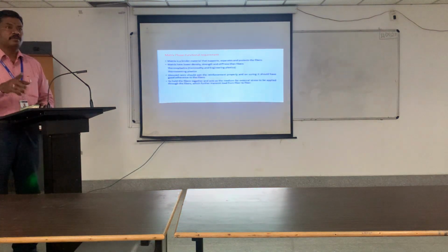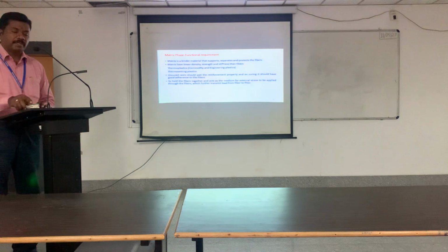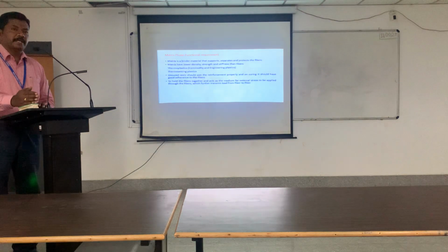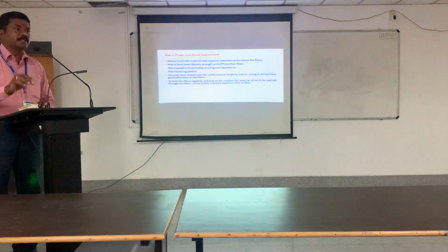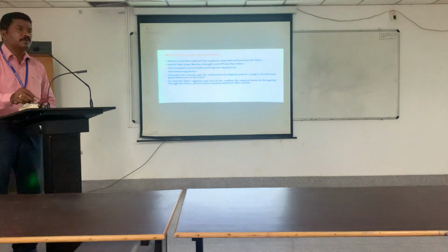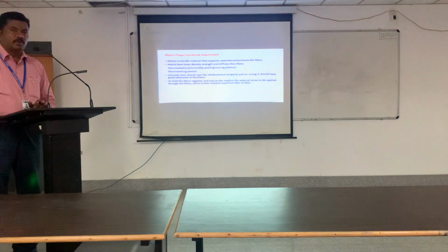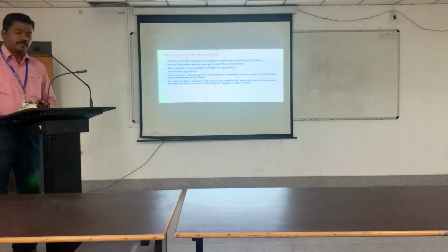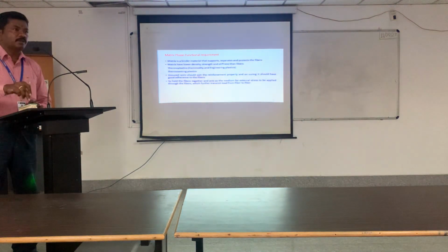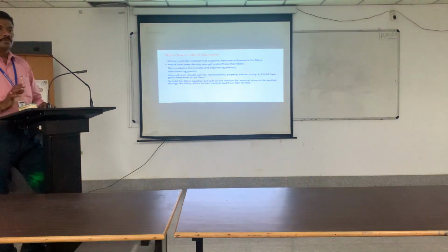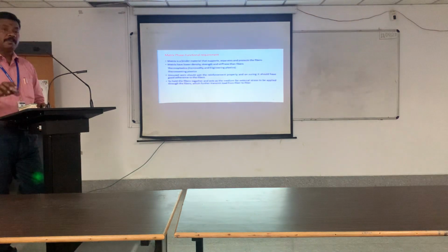That means that the passages will be already created. So, if the brick is placed on the wall, and if you place some amount of the cement material over the brick, wherever a path is already created, through that path the cement will try to slightly enter. If it enters, the bonding strength will be good. So if you don't dip the brick and if you just put the cement mixture over it, then the cement mixture will not get into the pores. So that is why the bonding strength of the composite purely depends on wettability of the reinforcement, how much it is being wetted.